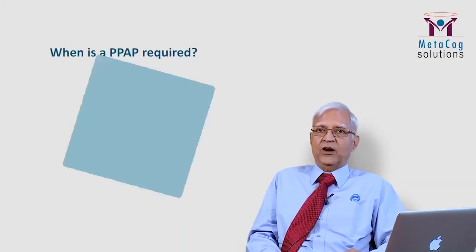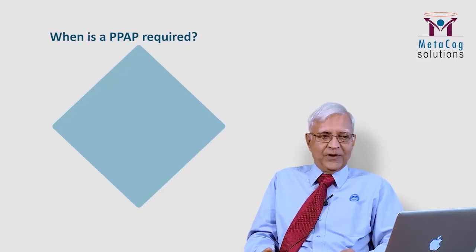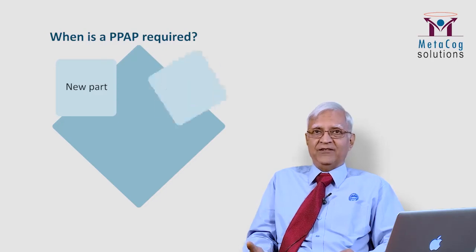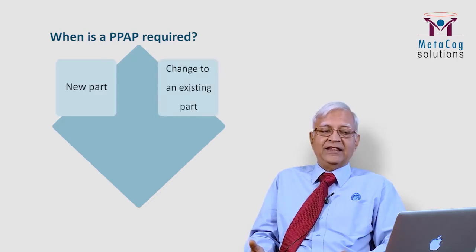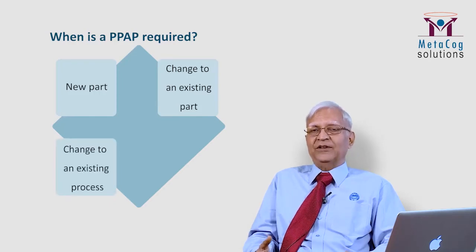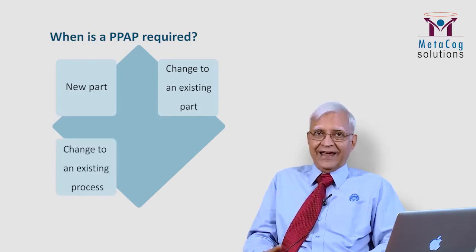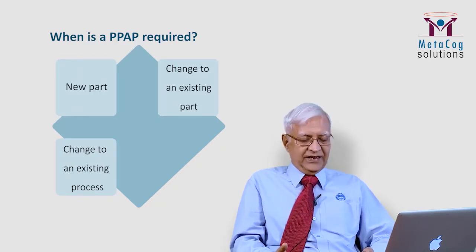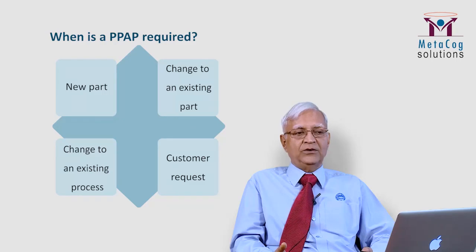Typically, a PPAP is required when you are making a new part, or when there is a change to an existing part. If there is a change to the existing process which the supplier wants to make, again the PPAP is required, or if the customer requests it, then you will have to do that.